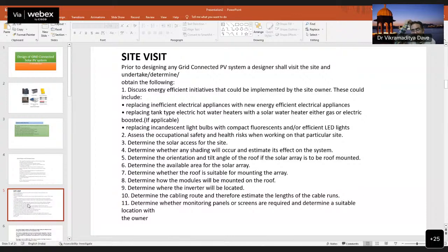Okay, so it is better that if you can install your solar panel at an angle of 25 degree, then it will absorb maximum solar radiations when placed in the south direction. If it is installed at 10 degree or 45 degree, then the solar radiation absorbed will be less in comparison to when it is tilted at an angle of its latitude.